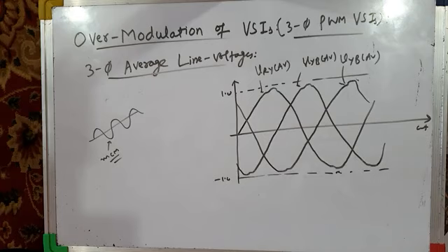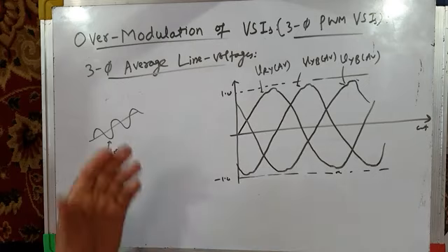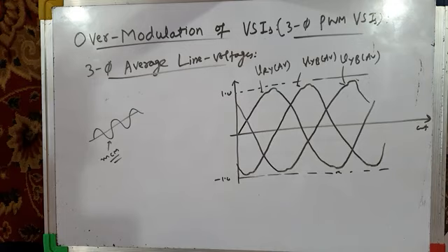But in the line voltages and in the phase voltages, these common mode signals get cancelled. So even if your pole voltage gets distorted, line voltages and phase voltages, which are actual inverter output voltages, retain their sinusoidal pattern. The instantaneous average line voltages and phase voltages in bus clamping PWM techniques and in third harmonic injection PWM techniques are sinusoidal.